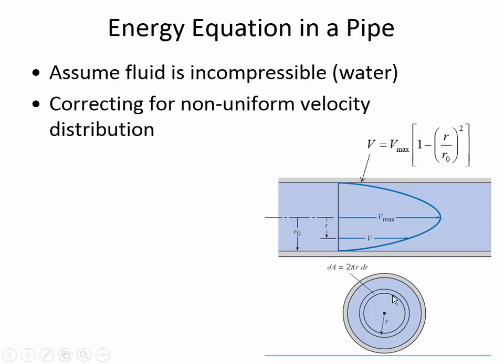So here, if we are just using the average velocity and squaring it, the problem is that the highest point, this tip of the laminar profile, is being undercounted when you compare the predicted velocity head to the overall velocity head. And so the way that we can account for that is by calculating an alpha.